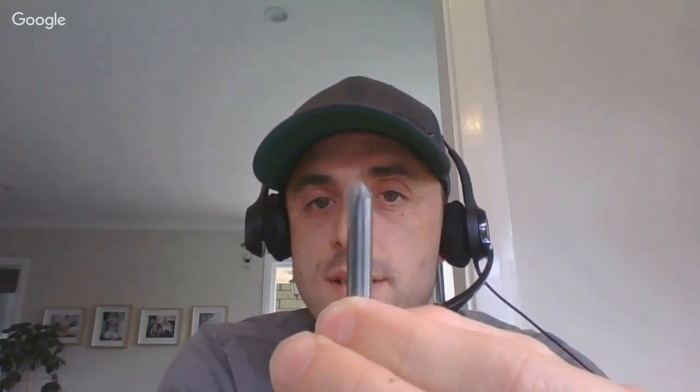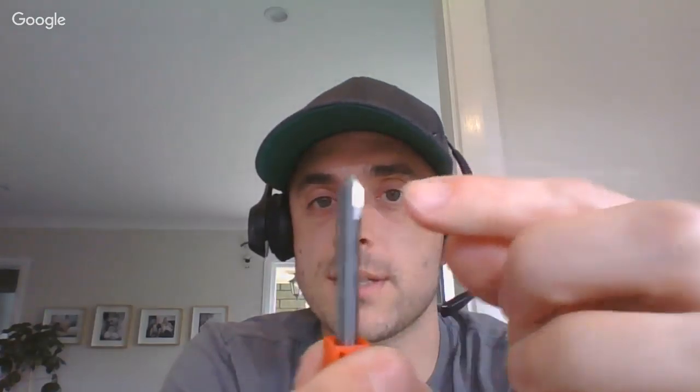So with small tools, in something like Perspex, there's a number of things you have to think about. If you're going down in diameter, the stability of that tool then becomes a problem, so stopping it from breaking gets difficult. But RPM is the other problem, and you need to be spinning those really, really fast to cut effectively. There is another factor, which is if you have what we call run out, where the tool is not spinning on its axis, but now it's starting to wobble as it rotates round, then that can be a real problem for tiny tools as well, because it's imparting loads on the cutter that can snap them.